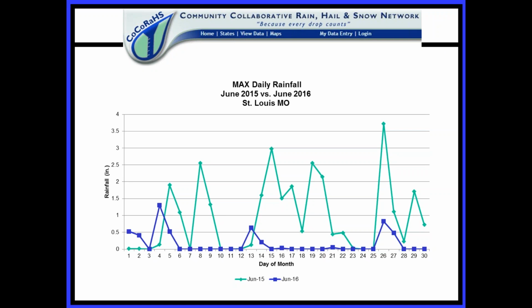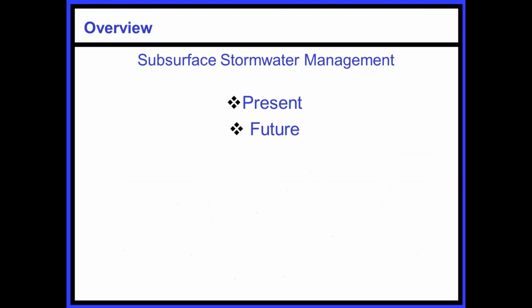In this particular June, the plants that need that water to survive aren't getting any water, or only a couple of days during that month had water. The challenge with bioretention in one respect is they're very arid soils. They're intended to drain very rapidly. Unfortunately, the downside of that is if it doesn't get occasional rain, it tends to work against that environment.